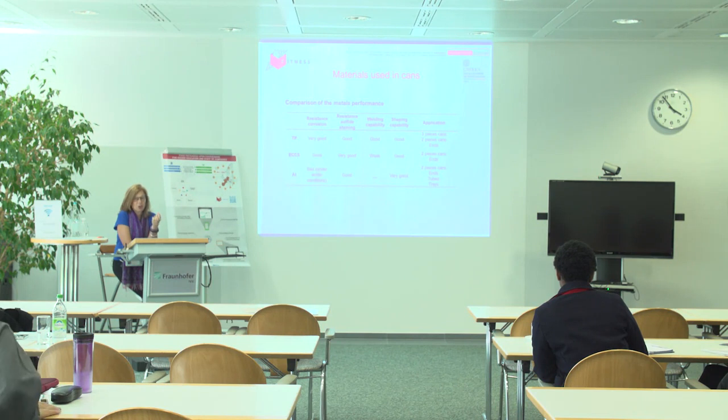This is not called corrosion, it is another type of interaction. Aluminum has good resistance to this sulfide staining because it does not have tin, it does not have iron, so the reaction cannot occur. Like here, in this tin-free steel, with the sulfide staining, the reaction with the tin cannot occur, just with the iron.